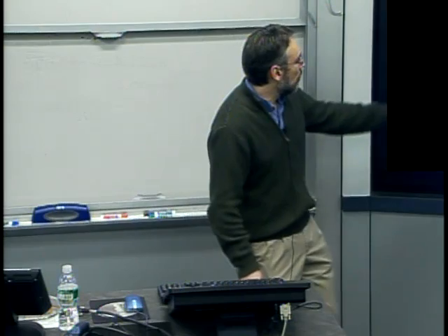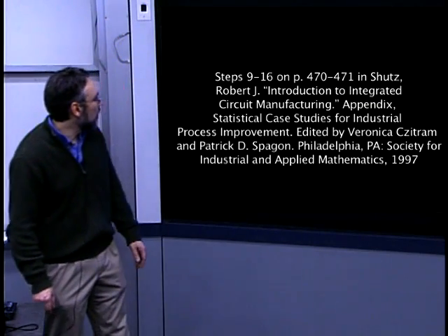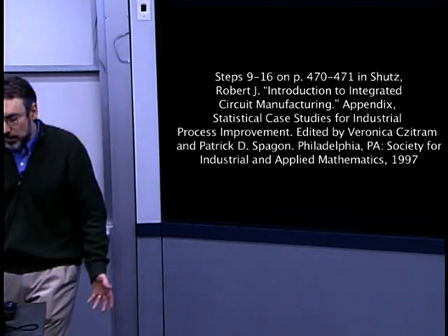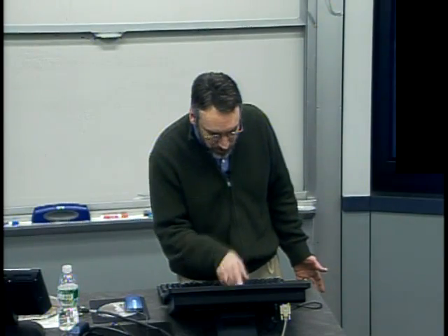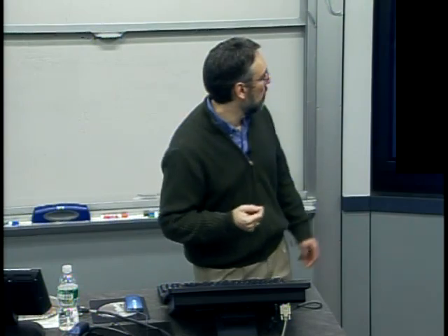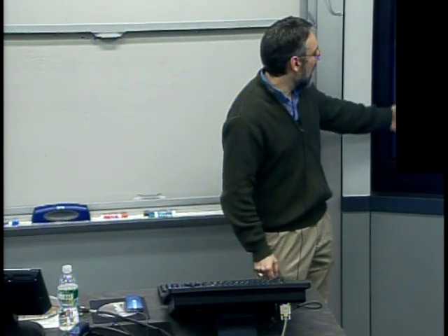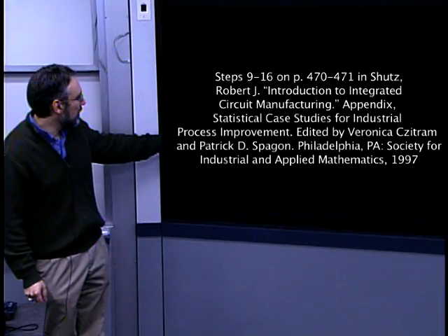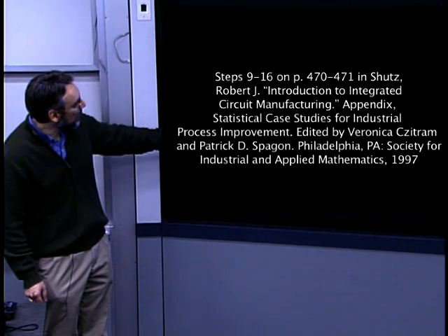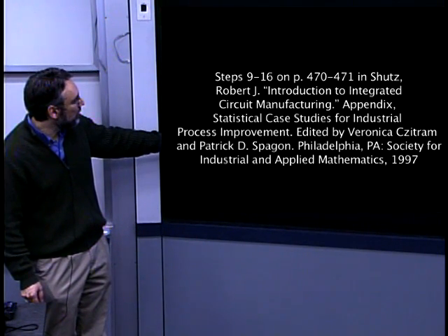Essentially, what we want to do with this yellow layer is build up an insulating layer. So I think a new layer of silicon dioxide is deposited. In this case, it's not thermally grown through that chemical reaction of oxide and silicon because I've already got polysilicon. I guess it actually might work in this case. I've already got a very thick layer of silicon.